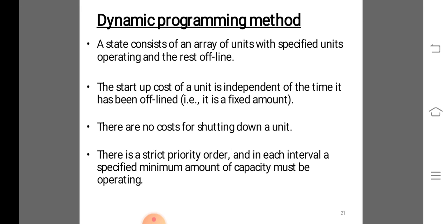The forward approach has distinct advantages in solving generator unit commitment. For example, if the startup cost of a unit is a function of the time it has been offline, its temperature, then a forward dynamic programming approach is more suitable since the previous history of the unit can be computed at each stage.